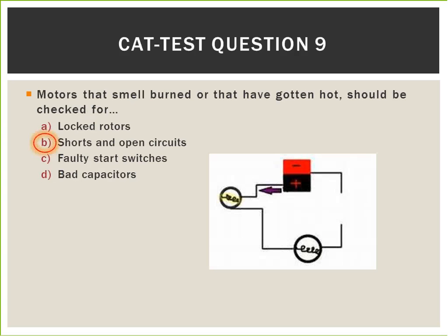Though answer A, a locked rotor, could cause the motor to heat up, the cause could also be from the motor bearings, and therefore not the motor. Answers C and D are not the best answers because faulty switches and bad capacitors will likely not make the motor hot. The most likely cause is shorts and open circuits, so the best answer here is answer B.